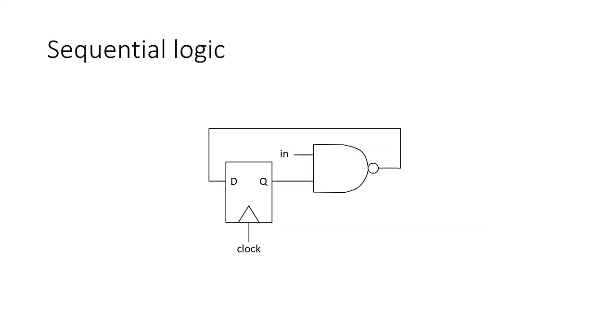Sequential logic is another key abstraction. Rather than just let these circuits run, we use a clock to manage how we go through a set of values. The box is a register that holds a value. When it reads a new value is managed by the clock signal at the bottom. It will then provide that stored value to the output, which can be used by logic. When the clock commands, a new value can be read into the register.